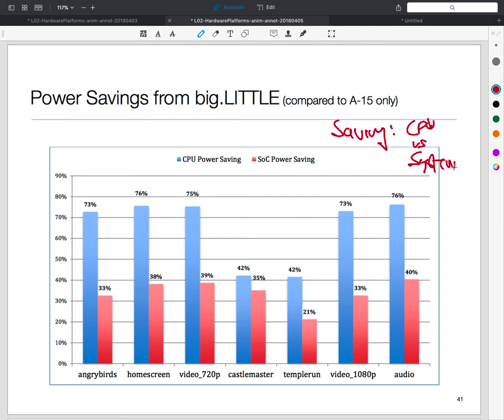For example, very loosely, ignoring sensing, embedded systems do 3 things, right? They process data, they store data, and they communicate data. Processing and storing in RAM tend to be cheaper. Communicating wirelessly tends to be very expensive. We'll talk about it later, but loosely speaking, if I were to send a bit across the room versus execute one instruction, sending a bit across the room would probably be 10 to 100x more expensive.